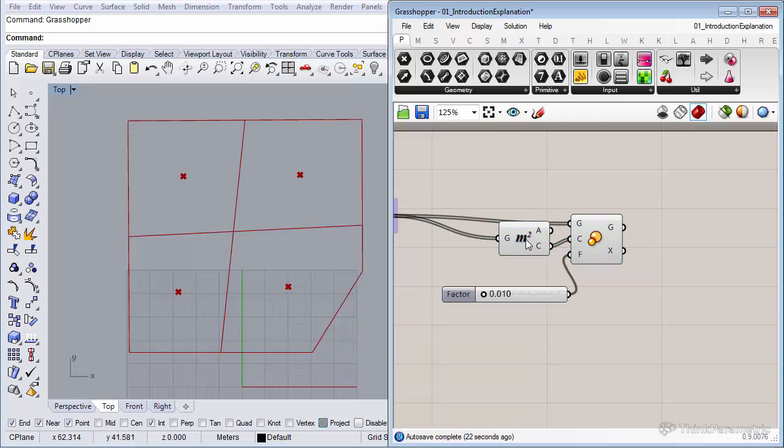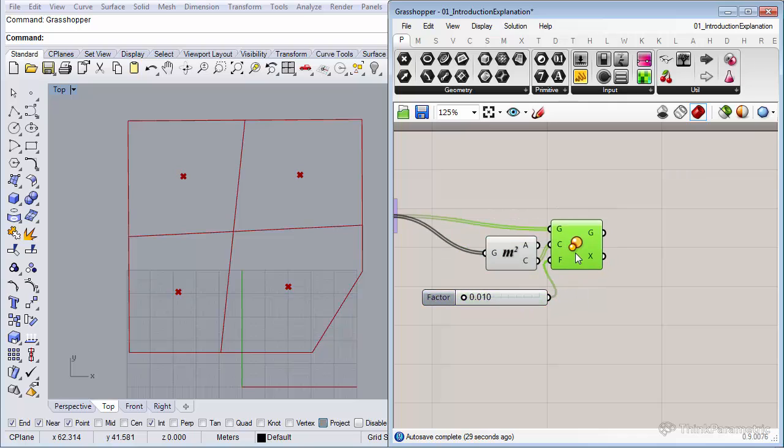Nice. So what we're going to do now is loft the inner with the outer polyline, so we get a surface. The only thing is that that surface will consist of multiple surfaces, resulting in a poly surface. But in the end, we want to have just one surface, let's say.